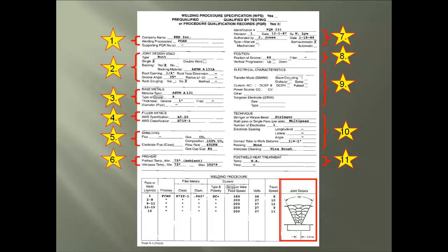To start, here is what the weld joint in this PQR will actually look like, and we have a groove weld. Does it match the line items for positions above? Remember, the G stands for groove welds, but you will be surprised how often this simple step is incorrect, which makes this form not in compliance for proceeding with any production welding.